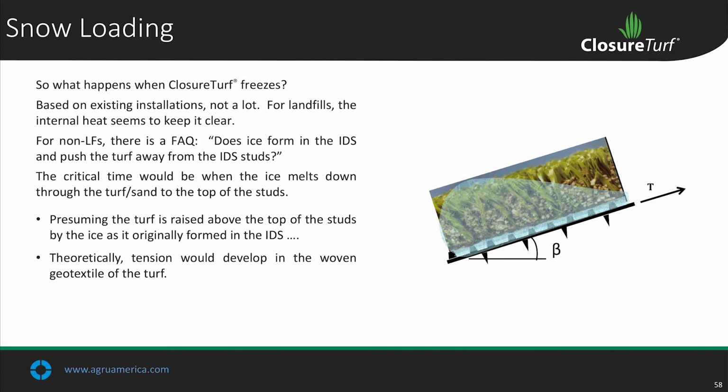Well, the critical time would be when the ice melts down through the turf sand to the top of the studs, so that you've got a layer of ice here that the turf is sitting on. Now, presuming the turf is raised above and is sitting on that ice, tension would develop in the woven geotextile of the turf, like so.